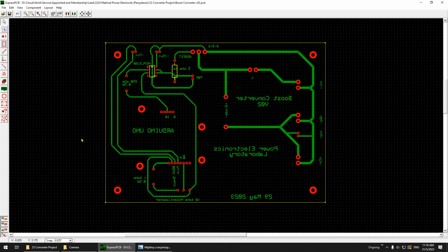At least have a space. Actually, for the tape, you need to tape this during the heat transfer process or printing process. You need to have a space. So for example, this is the size of the PCB. You need to have some sort of spacing. Or either you can make it smaller, then you can cut the board, no problem also. But for me, I don't want to cut the board, so I just follow the original size. For research, usually we don't care about the size, we make it large, easy to design. But if you want to do a product, you have to make it small.